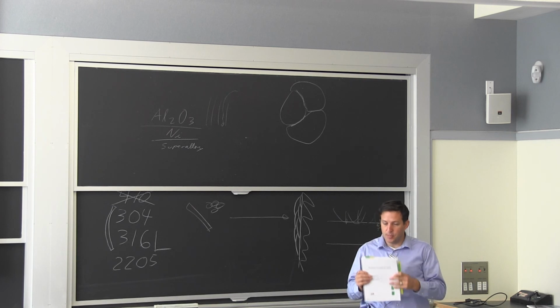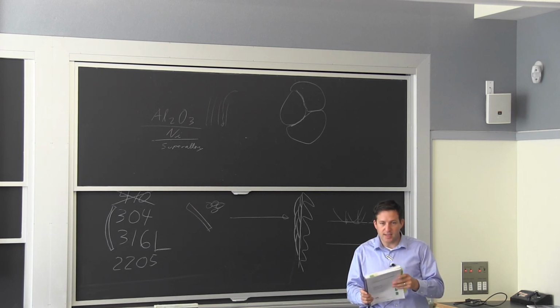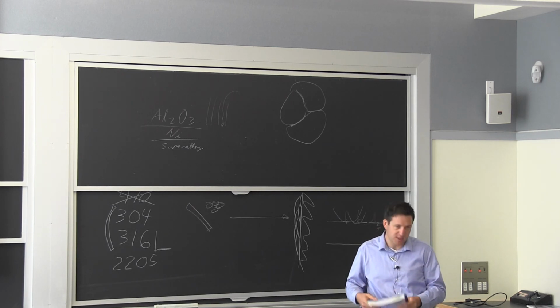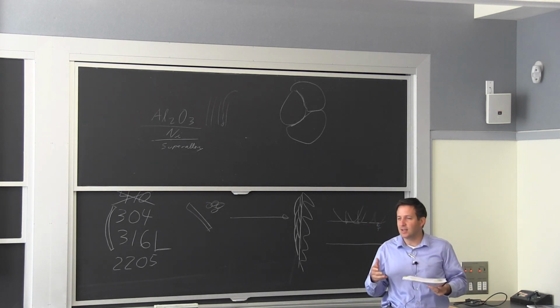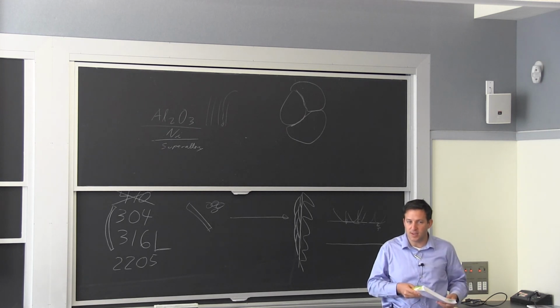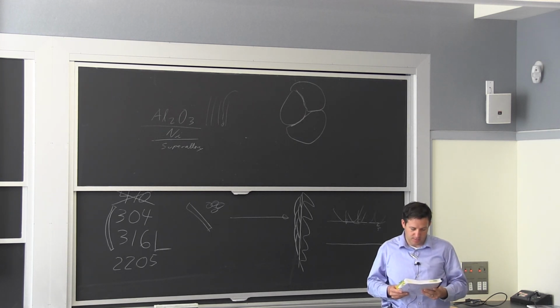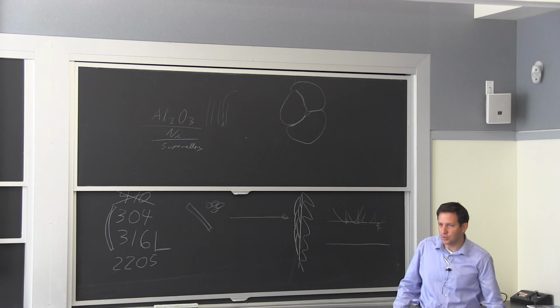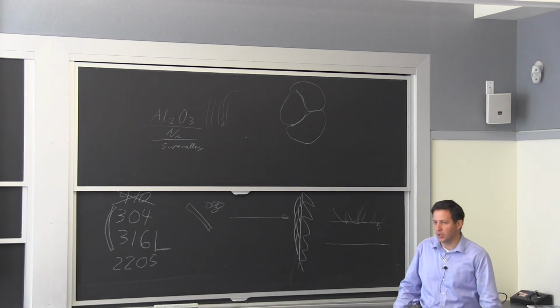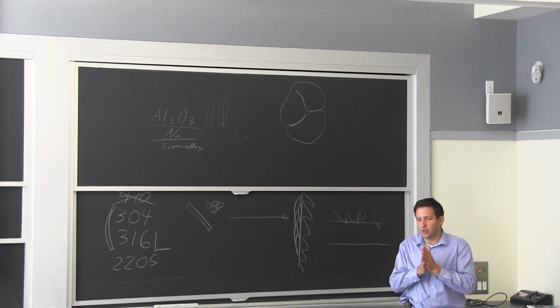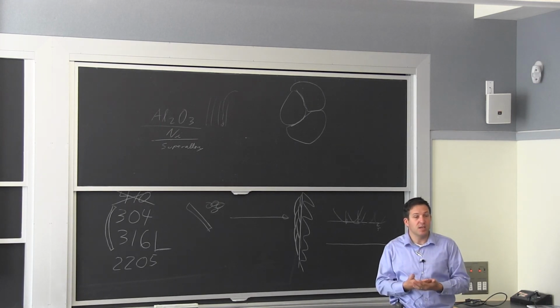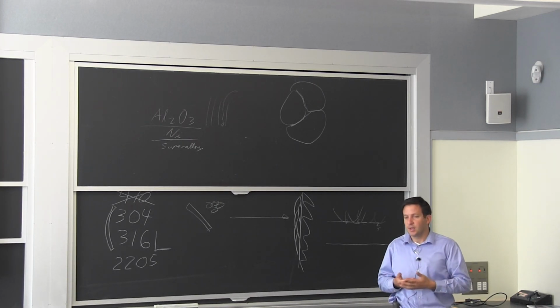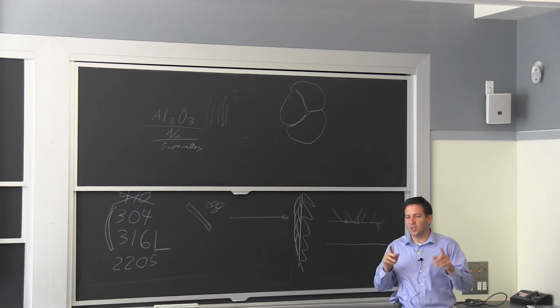And it's very important for you, if you're going to ask someone to give you a piece of steel, to think about, okay, what kind of standard steel do I want to use? There are ASTM standards for that. If you just say, I want this composition of steel, it's way, way too general. So you can have essentially a performance spec, which is more common. It says, I'm going to have these minimum mechanical properties. Or you can have kind of recipe specs.